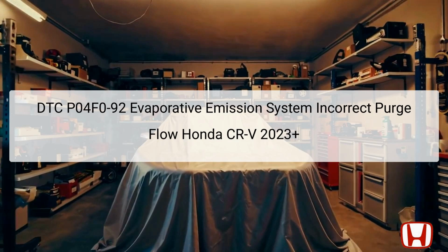The EVAP system is critical for reducing vehicle emissions, capturing fuel vapors, and rerouting them back into the intake manifold for combustion. The PCM monitors various sensors to determine if the EVAP canister purge valve is functioning correctly. If this valve does not allow fuel vapors to flow properly from the EVAP canister, it results in abnormal readings that trigger this specific DTC.